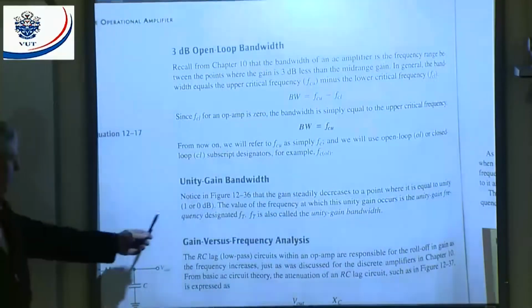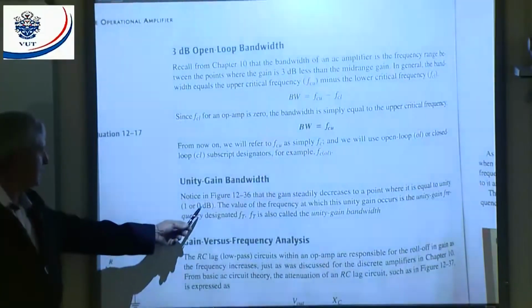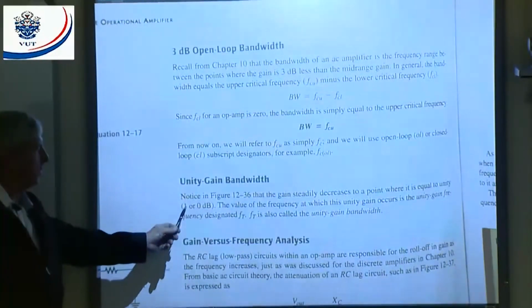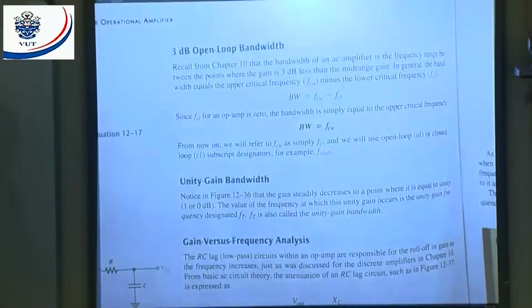All right, I just want to show you this, why we're going to do the next thing. We're going to look at the op-amp or the IC. Inside the IC, you will have the operational amplifier, and the output will be connected to an RC circuit like this. Now we're going to have a look at what is going to happen in an RC circuit like this. What will that be, a high-pass filter or a low-pass filter? That will be a low-pass filter, all right. That will give me filter action. That's why we're going to look at this RC circuit, all right.